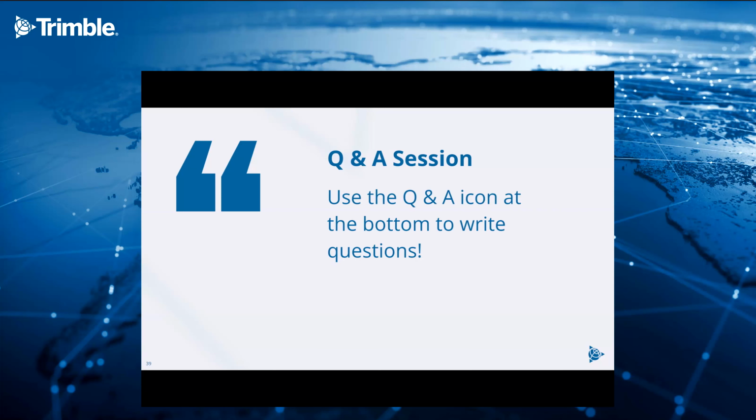I think the QC button itself is always a prerequisite for any type of processing, whether it's PP-RTX, PP-RTX2, single base, whatever. It always creates the GNSS-only solution before the solution gets merged with the IMU data, and this is a step that's always needed, and it has not changed.